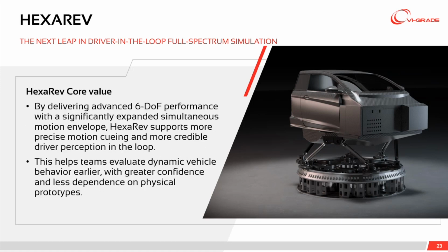This allows, of course, more natural motion cueing settings, easier motion cueing settings even for the engineer when he has to set up the correct parameters. And this, of course, helps the drivers and engineers evaluate the vehicle behavior under any condition for each frequency range. So this allows, for example, to run one-to-one maneuvers for ride comfort and NVH evaluations, or to do wide yaw movements combined with lateral and longitudinal when you're doing vehicle dynamics and hard handling simulations.